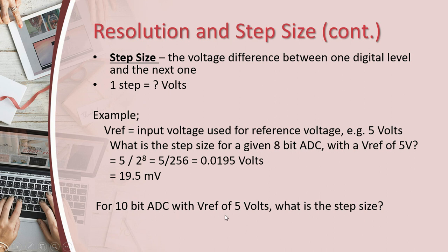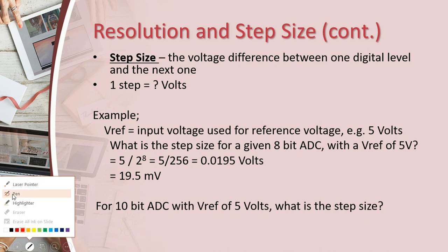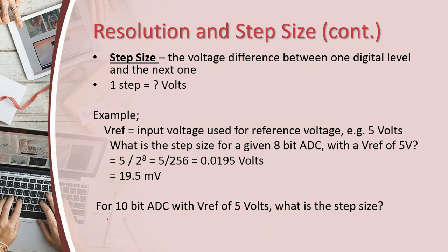Now, just simple exercise. For 10 bit of ADC, we have 5 volts. So what is the step size? Same equation like above. 5 volt divided by 2 power of 10. And then you will have the answer. Very simple.